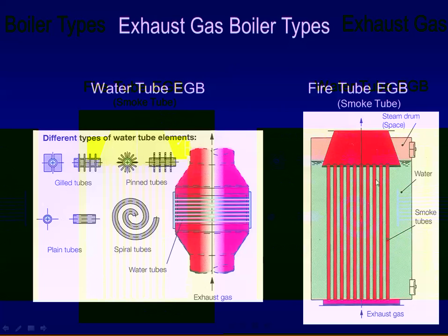Now, while I'm here and thinking about it, let's talk about that a little bit. As the gases move up through that tube, we're burning a very low-grade heavy fuel oil today that produces a large amount of soot. You need the velocity of the gas running through the boiler to be sufficient to carry it out, and then it can drop down on the main decks and irritate the mates. You don't want the flow rate to be too low, so the heavy particles just fall back down and lay on these tubes.